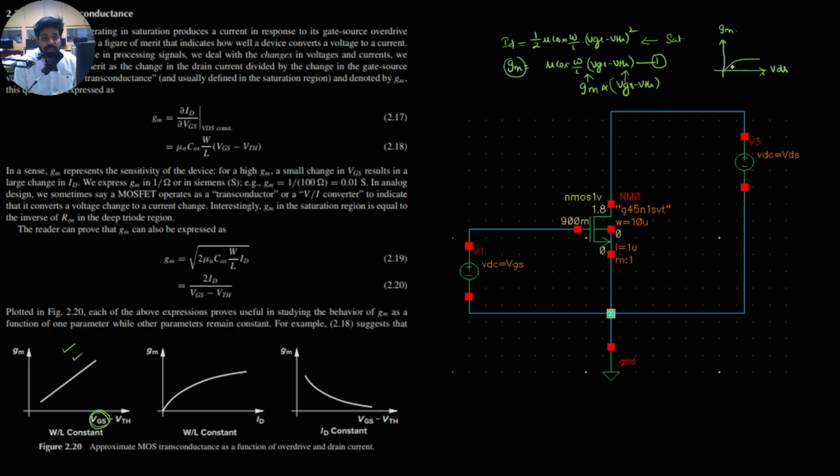So this is one case, this is another case, this is another case, like that I have all the plots. This is the VGS 0.6, this is 0.7, 0.8, 0.9, that is what the sweep values of VGS you took. Now this is the independent variable, this is also an independent variable, this is the dependent variable.